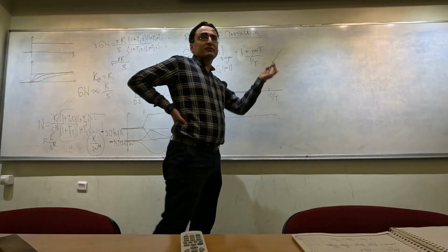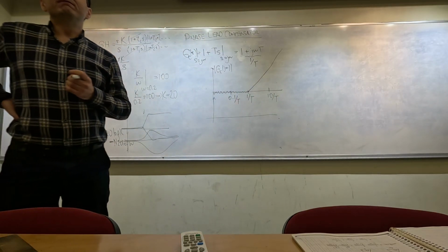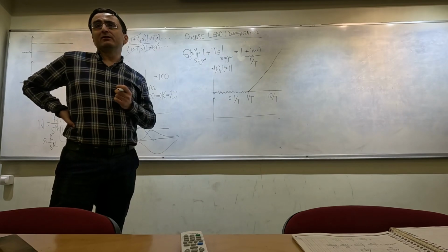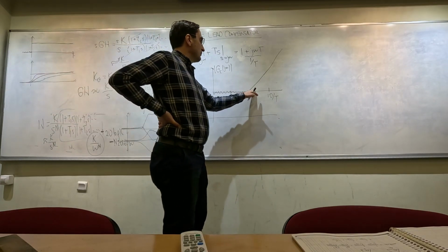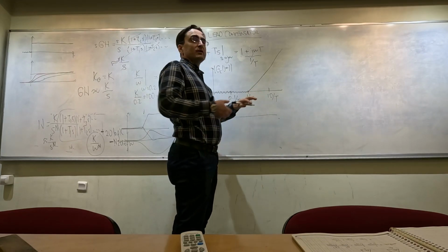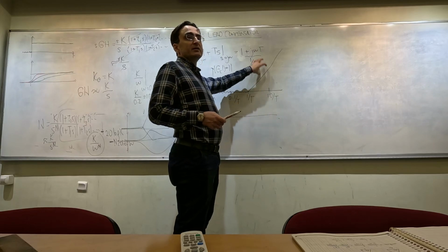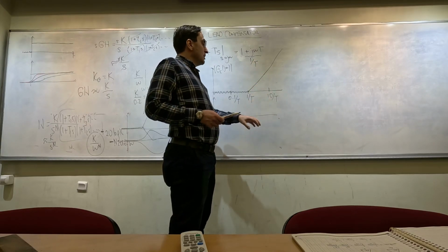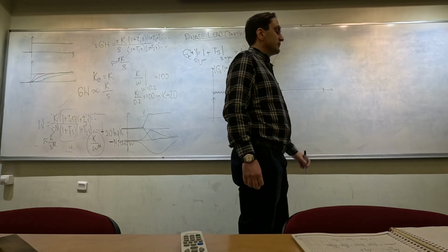So here, do you think this frequency response for our controller is fine? When we don't have any noise in our system, this is quite fine. If the input frequencies are somewhere here, then we are going to get a nice derivative effect. But there is usually some noise at very high frequencies. Okay?